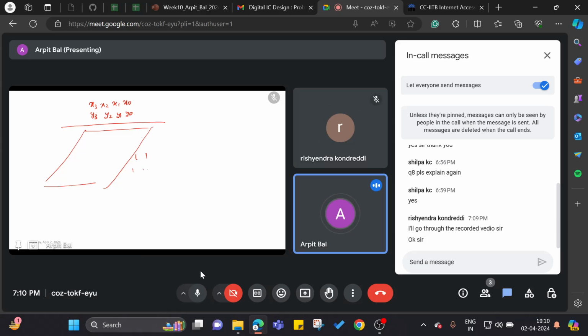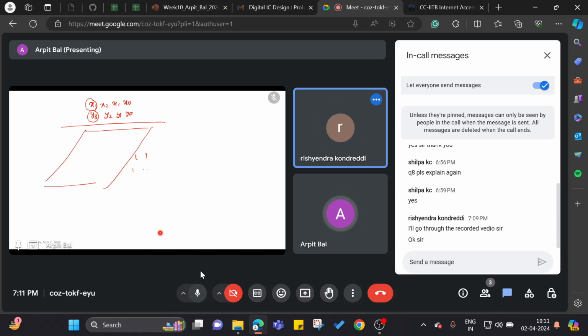So this represents the sign bit, right? Y3. If y3 is multiplied with anything, it should be a negative number, correct? So whenever we do the evaluation, the complete addition process, the entire partial product should be negated, right? Let me give you one example.